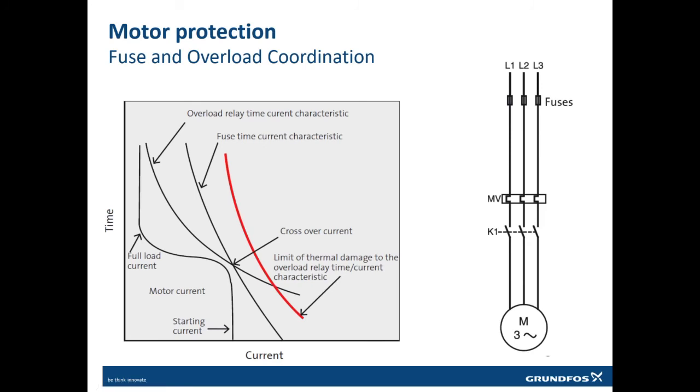So this is the combination of all the protections. This was the full load current, which is taken in the very beginning. This is the motor starting current, and then the motor goes to the full load current, at which it will operate throughout. This is the overload current, overload relay. Whenever it goes here, this will trip, but if it goes suddenly very high, then a fuse will break.